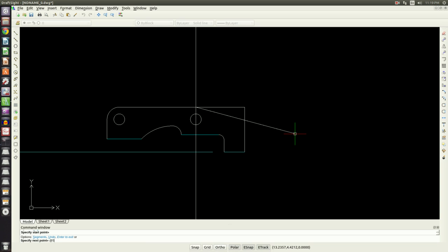So I'll use 5. And then type less than. And since I'm moving down, I'm going to use a negative angle, and it's negative 15 degrees. And then we'll offset 1.6, our infinity line.